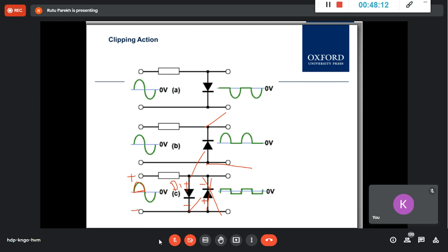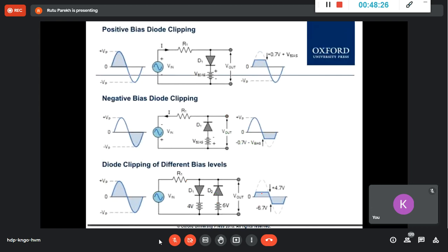But in some design requirement or circuit requirement, you need a waveform that is from -1 to +1, or -1.5 to +1, or +2 to -0.5. Those kinds of waveforms, you need some input that you want to give. Positive can be a different voltage, negative also different or the same, whatever you want, not just 0.7. It can be +2 to -2 volt, a rectangular wave or something like that. Then what you do is add this voltage supply to this diode.